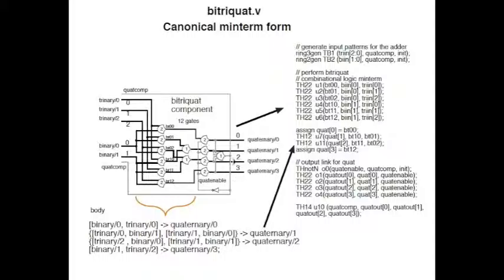And the completeness criterion states that when an output transitions to data, when one rail transitions to data, it implies that the input is completely transitioned to data, that data wavefront has flowed completely through the circuit, and that's the correct resolution of the presented input. So you can see if one rail of trinary transitions to data and one rail of binary transitions to data, only one of these gates will transition to data, and that transition will propagate through the circuit to the output, fulfilling the completeness criterion. And the completeness criterion works for the null also.